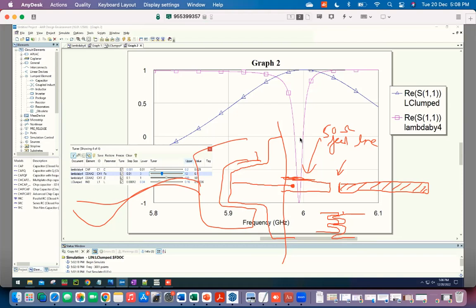So all of these connections, from this cable, which is a 50 ohm cable, to this male SMA connector, which is a 50 ohm connector, to this female connector, which is actually allowing you to launch onto the microstrip, all of this should ideally look like a long transmission line which ends at this point, with 50 ohm characteristic impedance.